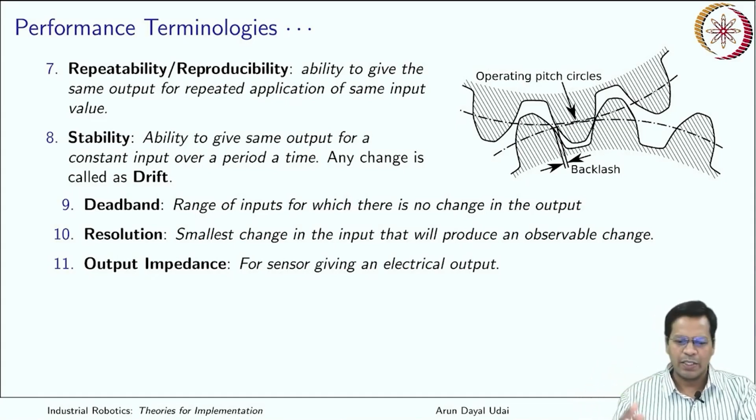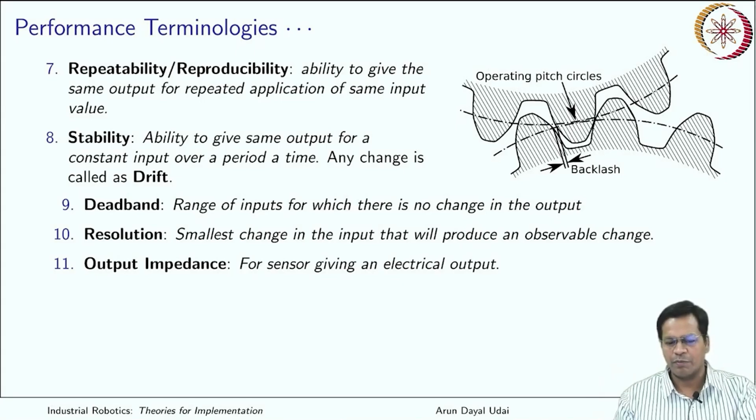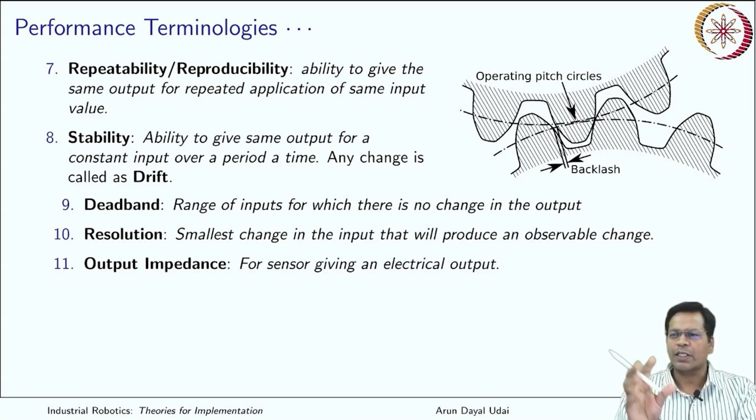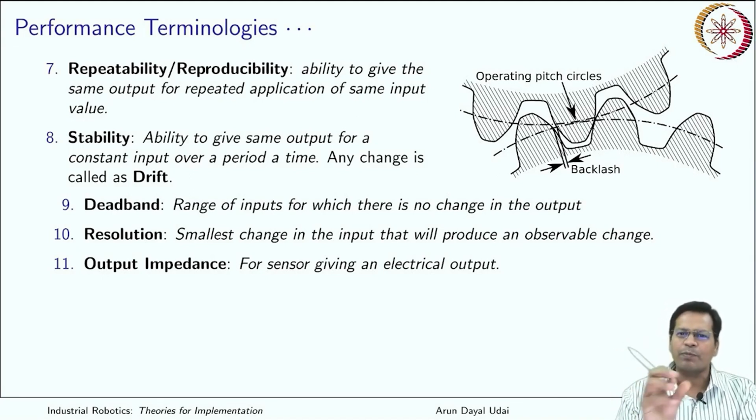Okay, so that is why this impedance is very, very important. Actually when you connect it to this, the total resistance of this device changes, because it becomes something like a parallel resistance. So the effective voltage across that changes. So connecting this device changes the property of this.